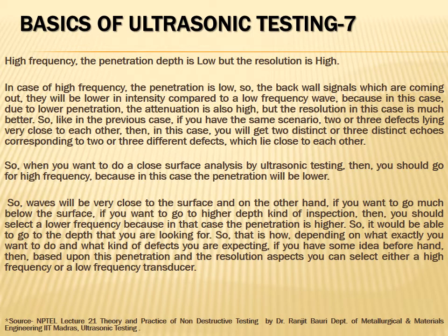In the same scenario, with two or three defects lying very close to each other, you will get two or three distinct echoes. In the low frequency case the signals overlap and merge, but here that overlapping does not happen. So high frequency gives you a high resolution at a low penetration.